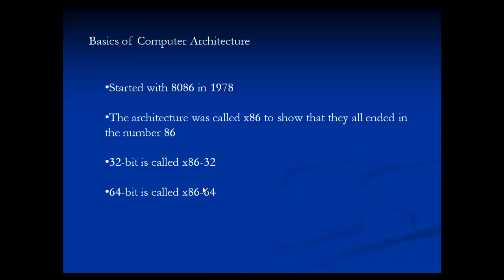The more ample the space in the CPU's registers, the more it can handle, especially in terms of utilizing the system memory. Now, a CPU with a 32-bit register can have a ceiling of 2 power 32 addresses within the register. This is equivalent to 4 gigabytes. Hence, it cannot support more than 4 GB of RAM. Whereas a 64-bit register can have 2 power 64 addresses, which is very huge.